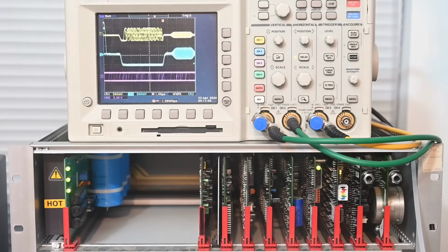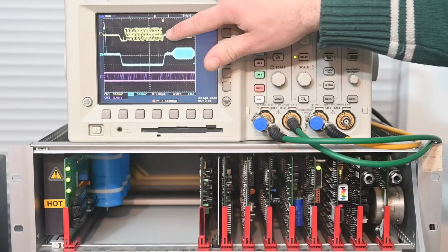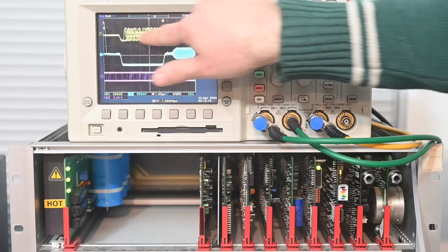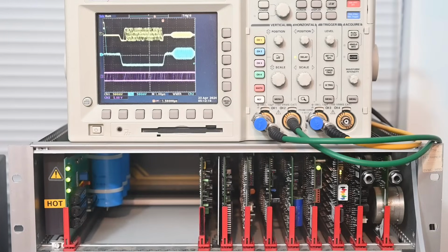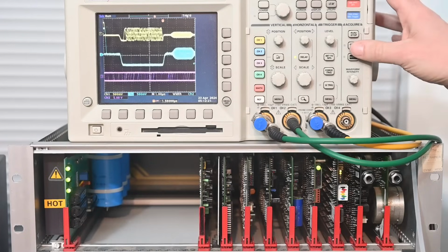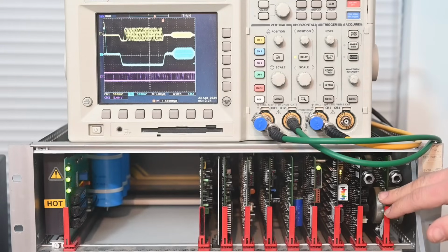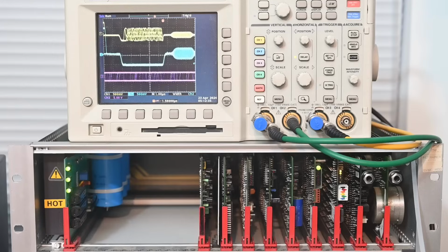And this is a key important point that I really want to get across about this system, which in the past some people have maybe not necessarily taken in, is that this signal here, this yellow signal, the viewing public never receives this. They only receive this recovered video signal. The data which is in this burst here is actually this purple trace down here. This is the NICAM serial bit stream coming out of the decoder. And in terms of what happens with this bit stream, well, there's a number of different things that can happen to it. It can go into the internal decoder, it can go into the internal monitoring decoder, and it can also, as I say, appear on that external interface and can be fed into a NICAM modulator digitally. Anyway, that's just a quick summary of the actual signals.